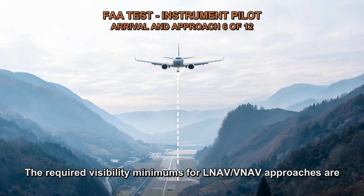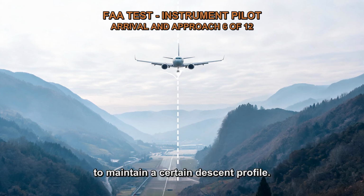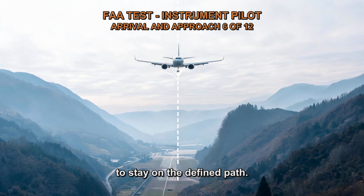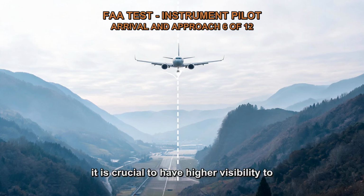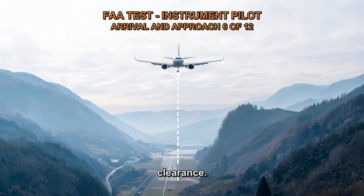The required visibility minimums for LNAV/VNAV approaches are often higher than those for LNAV alone because the vertical guidance component introduces an additional requirement to maintain a certain descent profile. By incorporating vertical guidance, the aircraft must maintain specific altitudes or vertical rates during the descent to stay on the defined path. If obstacles are present along the descent path, it is crucial to have higher visibility to ensure the pilot can visually identify and avoid these obstacles in order to maintain the required clearance.